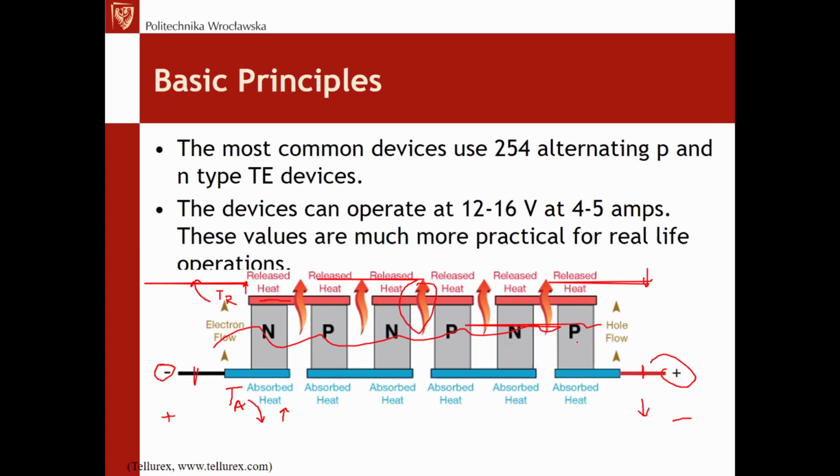On one side is the element, the only one we have, in fact, to pump heat in 2 directions just by changing the polarity of the electric signal. On the other side, it has the disadvantage of possibly positive feedback in case of the power loss and the temperature rise and the efficiency reduction in the Peltier element itself.